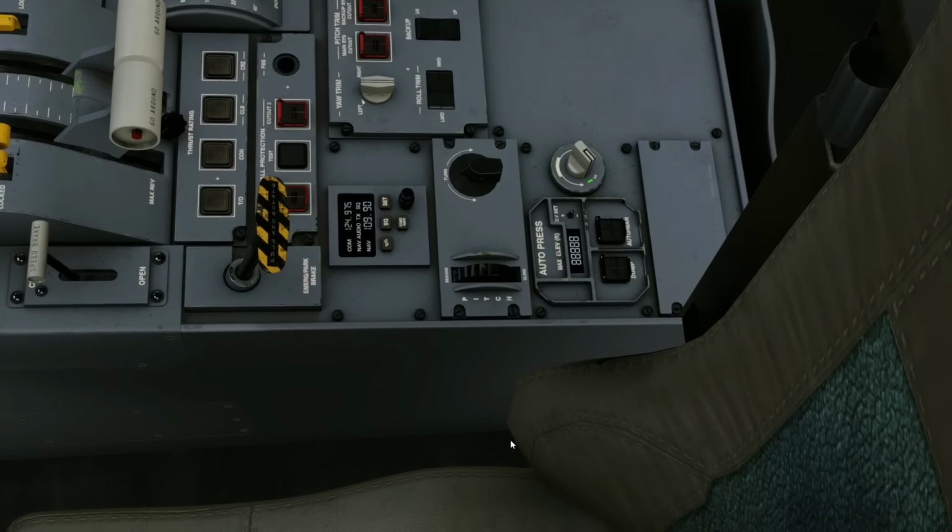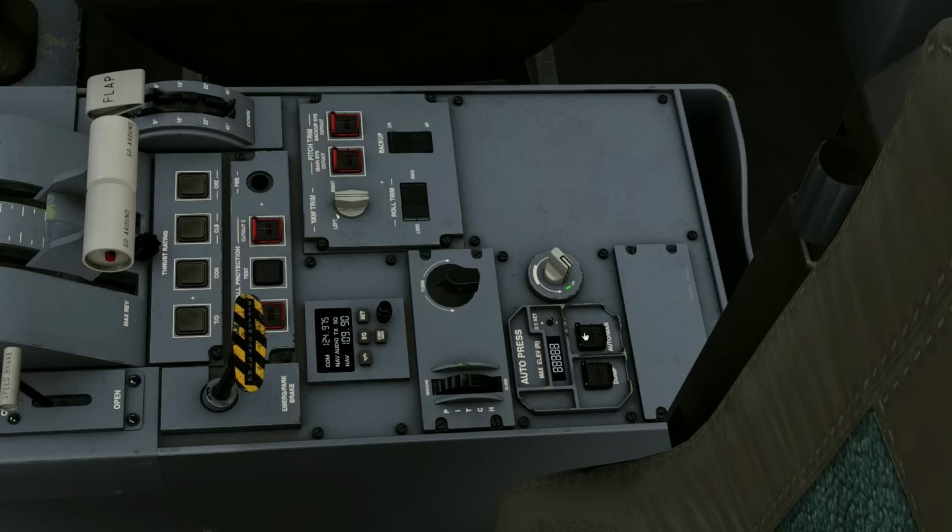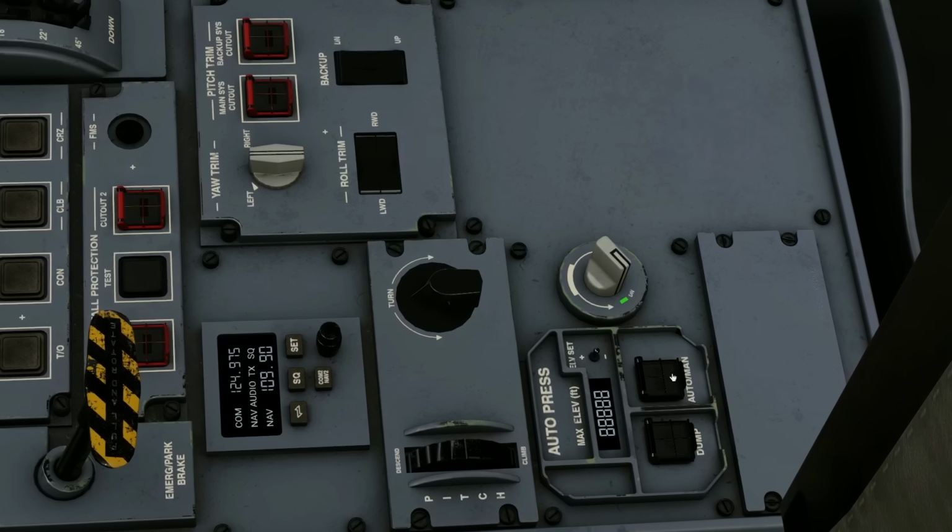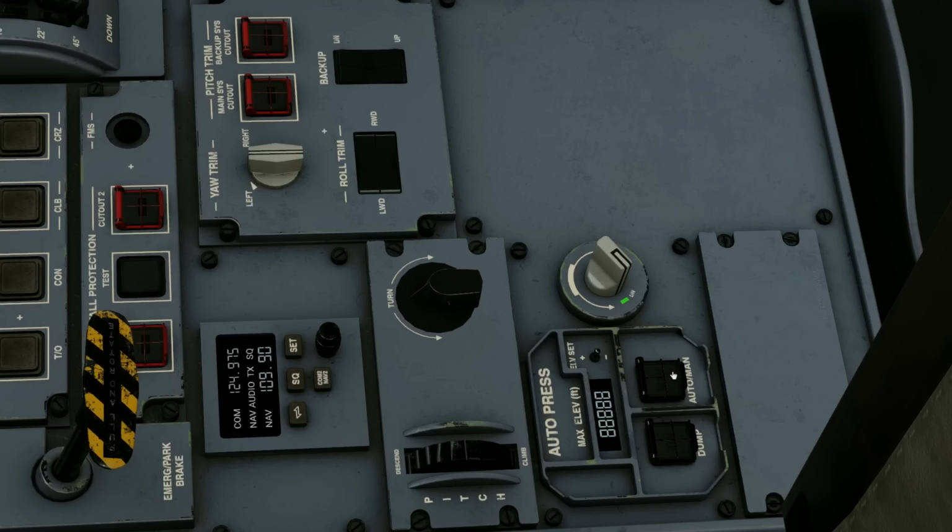Last new thing down here is the pressurization controller has been completely redone. The way that pressurization is controlled on this aircraft is we have two systems: the automatic system and the manual system. For the automatic system, which is where we are 99.999% of the time, we take this knob here, which actually controls the outflow valve position. If you turn it all the way counterclockwise to the green, and press it into the green detent, we're in the automatic mode. So this is an automatically controlled pressurization system now.